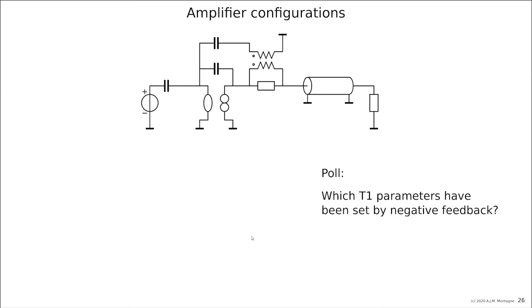And here we did another configuration. Here we sense the short circuit current. We have parallel feedback at the input, and then we sense again the current to the load, transform it into a voltage with a resistor, make a copy of this voltage and differentiate it again so that we can fix the output impedance. This is a nice thing to study for yourself. If you're not familiar with dual loop feedback, this is a nice study.